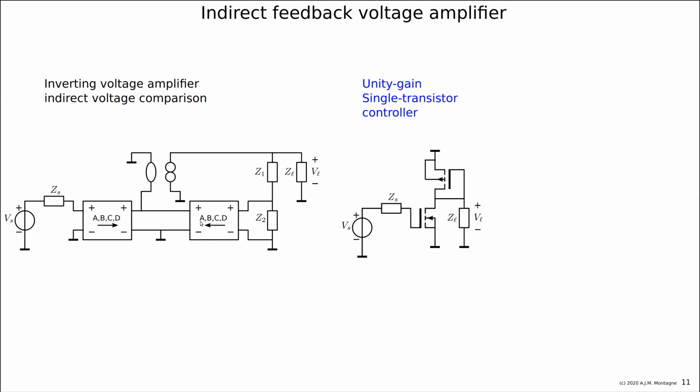Now, do again the same thing, make the upper transistor, make this, say, well, we have already gained the second transistor, and take a complementary device for this, and you get this schematic. And this is then a unity gain voltage mirror. And of course, since now you can see that the upper element is a 2-terminal element, you can also use the complementary version of it, which is N-type again, but flip the terminals. Because flipping the terminals and making it complementary is actually doing nothing.